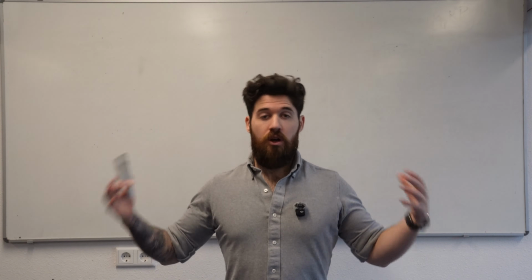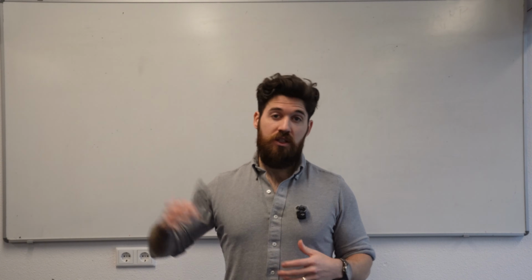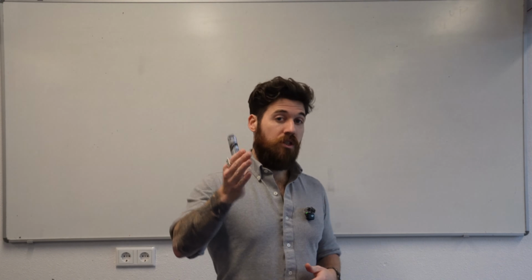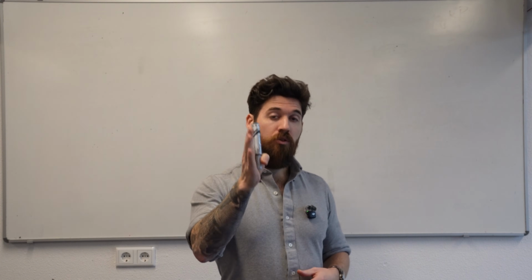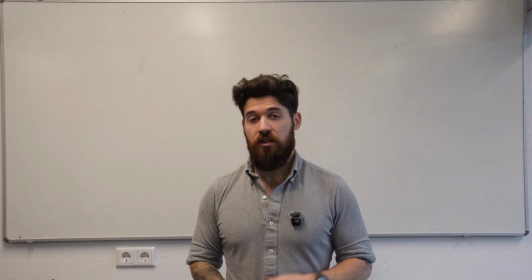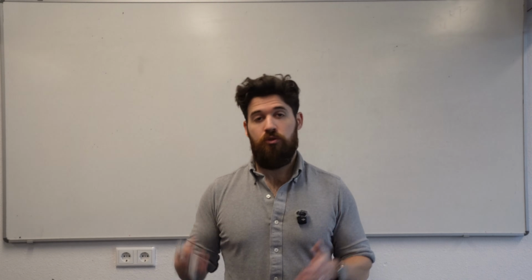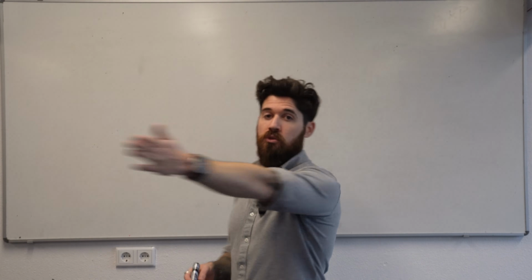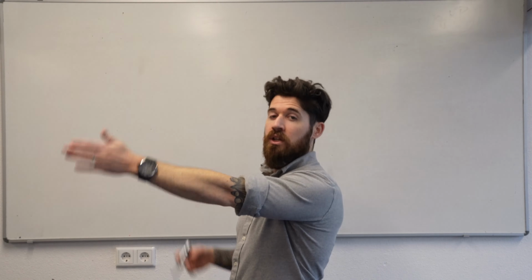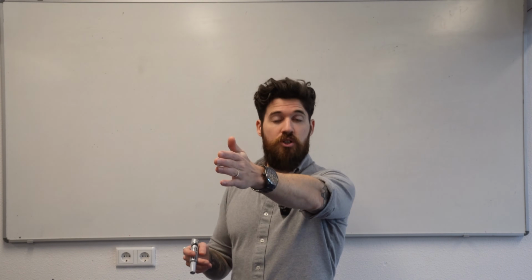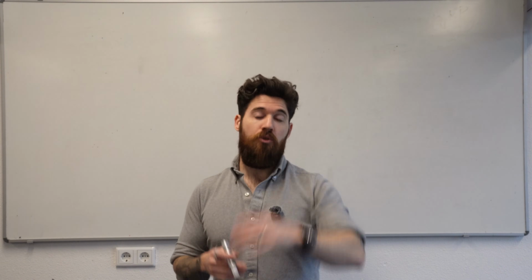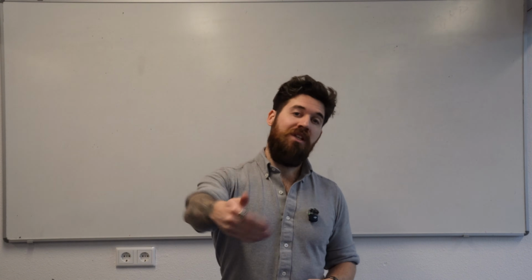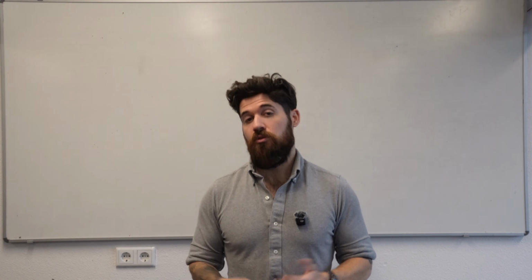For our turret, effectively, we need to find a way that the farther away we are from our goal, the faster we need to rotate the turret back, and the closer we are to the goal, the slower we need to move it back. That's the basis of proportional control. For example, if looking straight on is my goal, and I'm currently looking over here, the further away I am, the faster I should go. The closer I am, the slower I should go. So proportionally to how far away we are from our goal, we should be increasing and decreasing our motor speed.